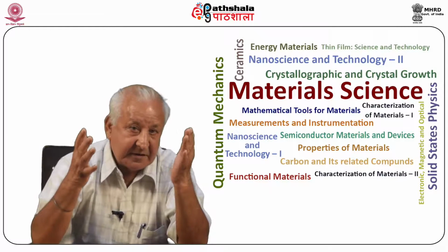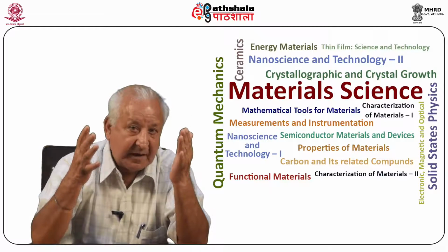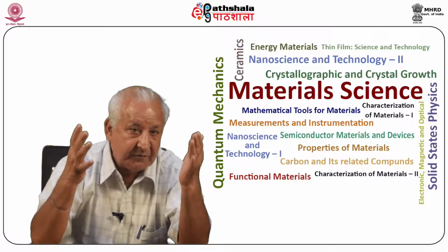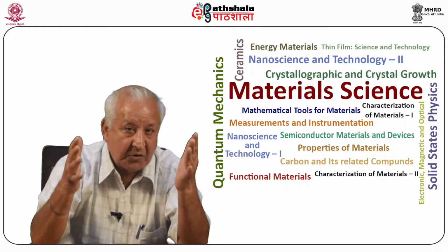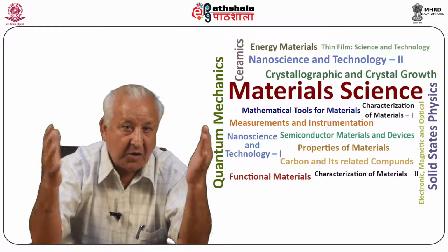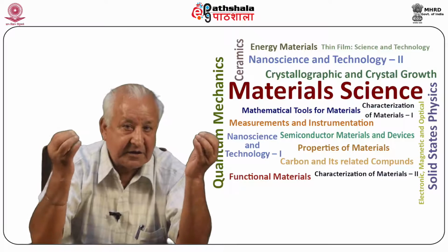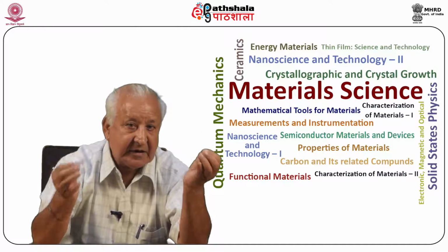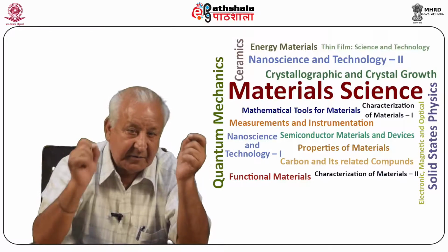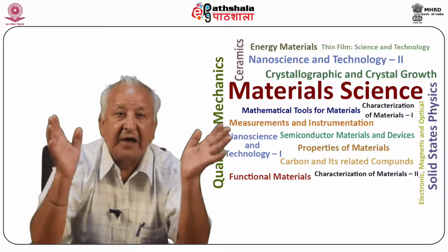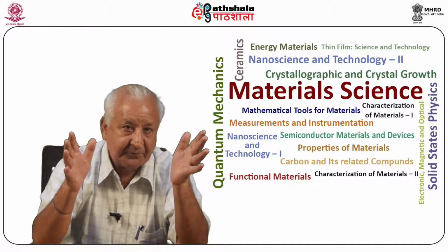The basic apparatus used for the growth of crystals by this method is shown in figure 31.4. The material to be grown as crystal is placed in a long boat with dimensions of 1 foot in length and 1 inch in diameter so that it is completely filled. Then a section of the material is melted with the help of narrow heating coils.